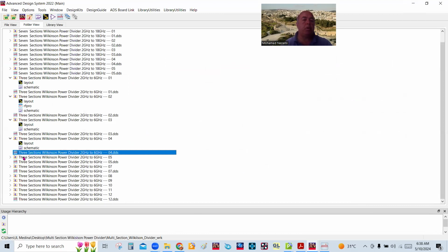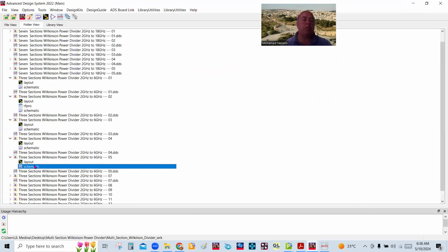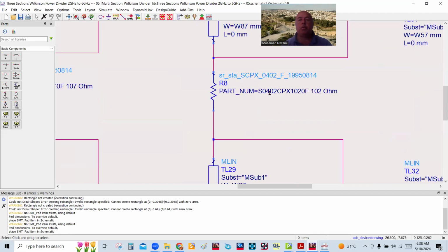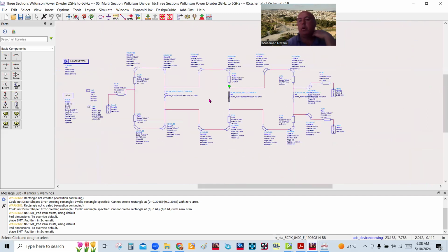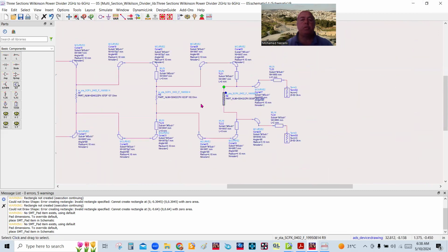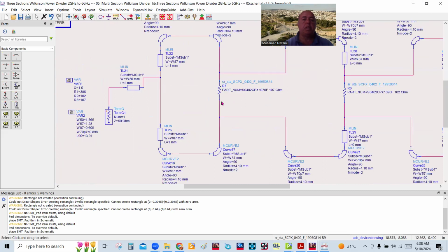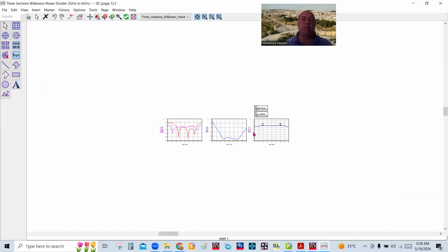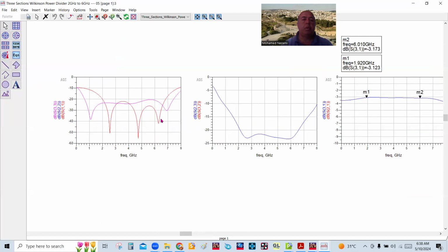So what we're going to do next is shift over to a smaller package resistor. And this is an 0402 package, okay, these resistors. And when we run this, of course, all of these resistors right now are 0402, same values. We didn't change anything. We would expect that we're going to get less parasitics, and yes, we do.